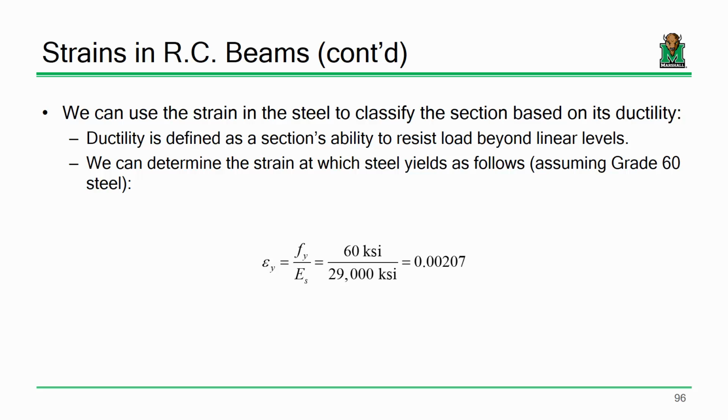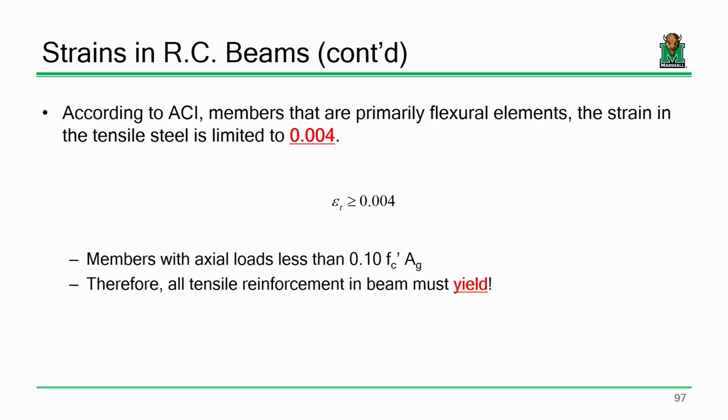If the steel will yield at about 0.002, we actually hope that we see like 0.006 or 0.007. That might seem kind of weird. You're like, what are you talking about, Dr. Mike? You actually hope that the steel yields? Actually, yes, I really want the steel to yield, and I'm going to explain why. I want it to yield. That might seem a little weird, but here's why.